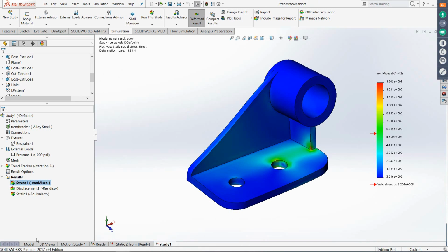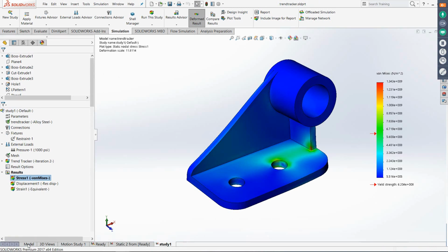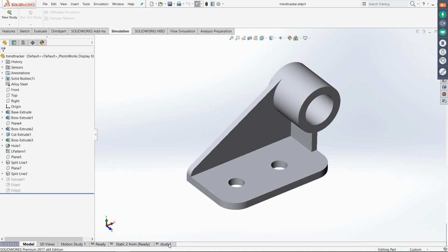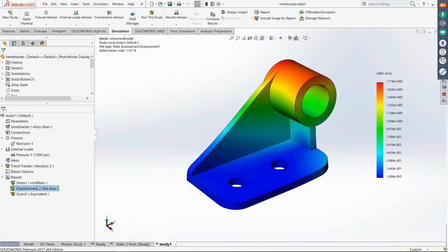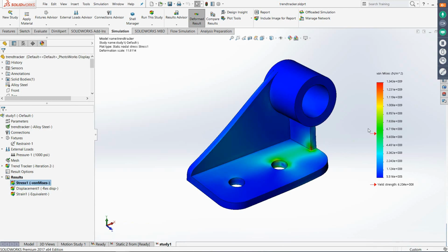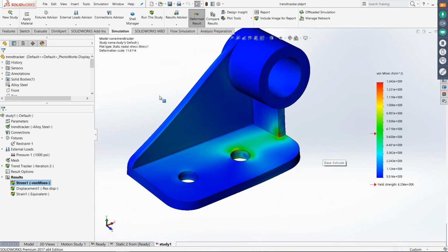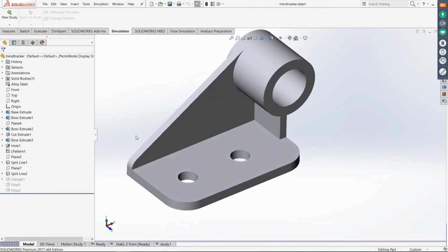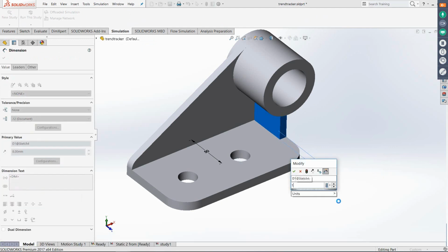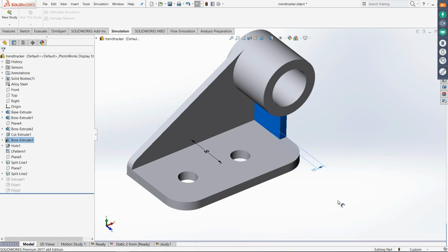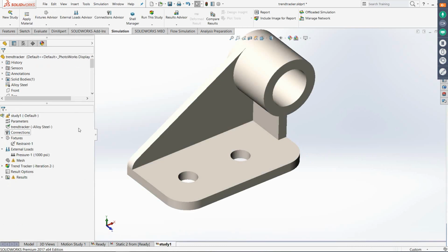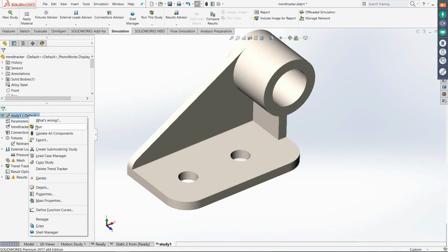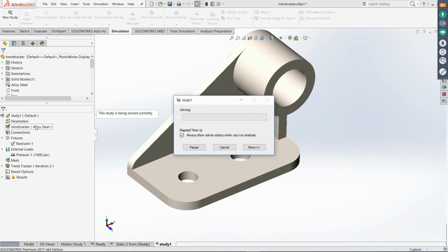Now I just need to do this, and as a designer I may be seeing the results. Let me check out the results. How do they look? Displacement, stresses, they are in the tune of 1.33. I am not happy with this result. I still want to play with the model. I get into the SolidWorks CAD part of it. I double click the entity. I double click again, change the value, and I am all set. Let me go back to the study, trigger the solution.